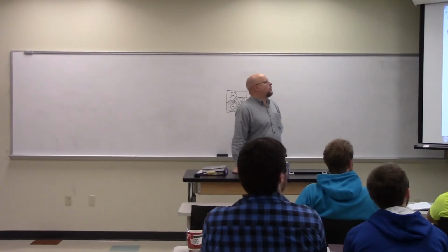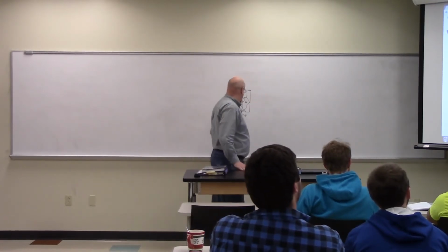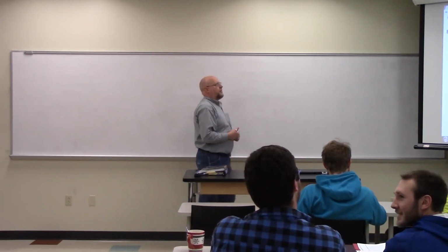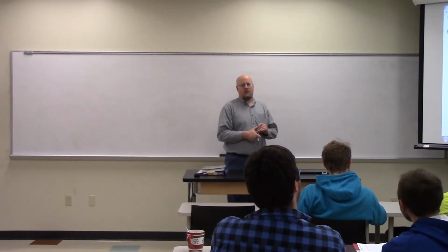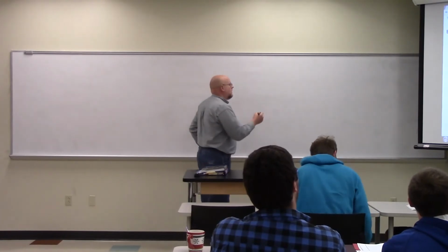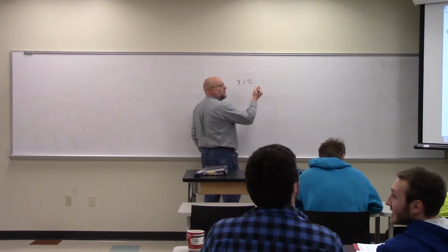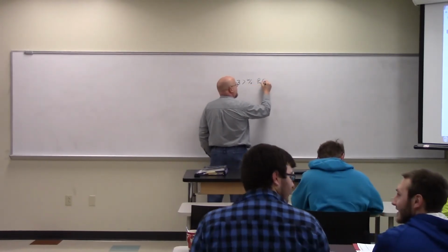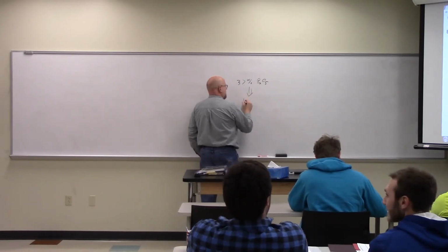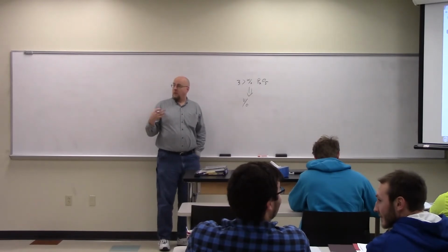Oh, yeah, the P2O5 density, the particles. Cool, thank you. Okay. So the key here is to translate from weight percent to volume percent. We're given 3.7 weight percent P2O5, and we have to transfer that into a volume percent, because then we can find the volume of each part.